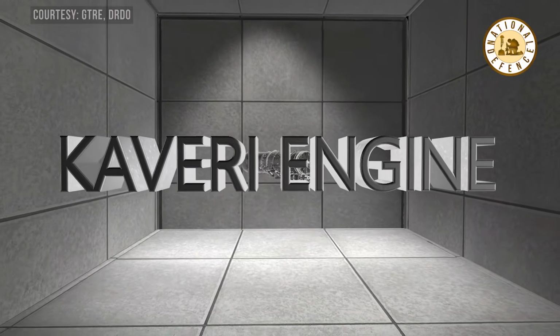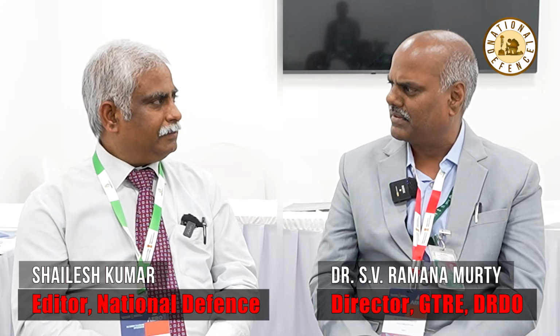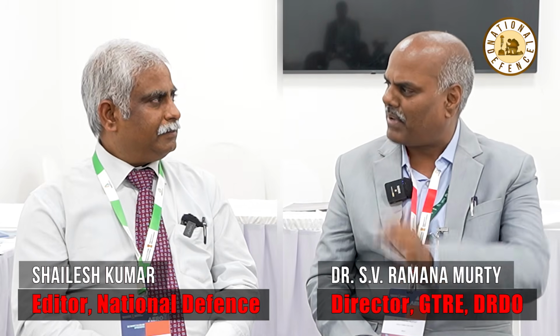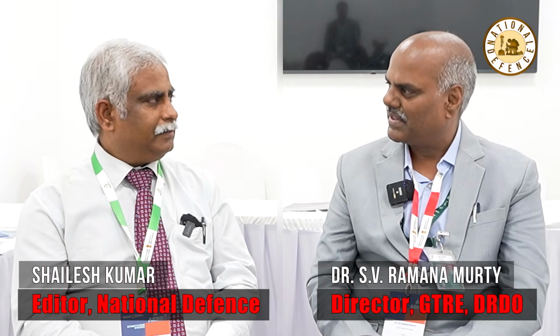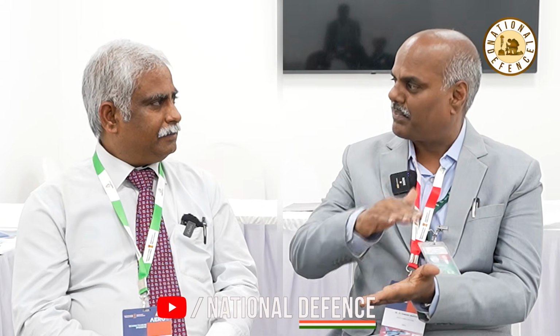Then very, very important, one of the latest trends in the technologies is powder metallurgy discs. There is a disc, the HP turbine disc. That is the highest stressed part in the engine. The running stresses will be almost above the yield point, near the plastic range actually.